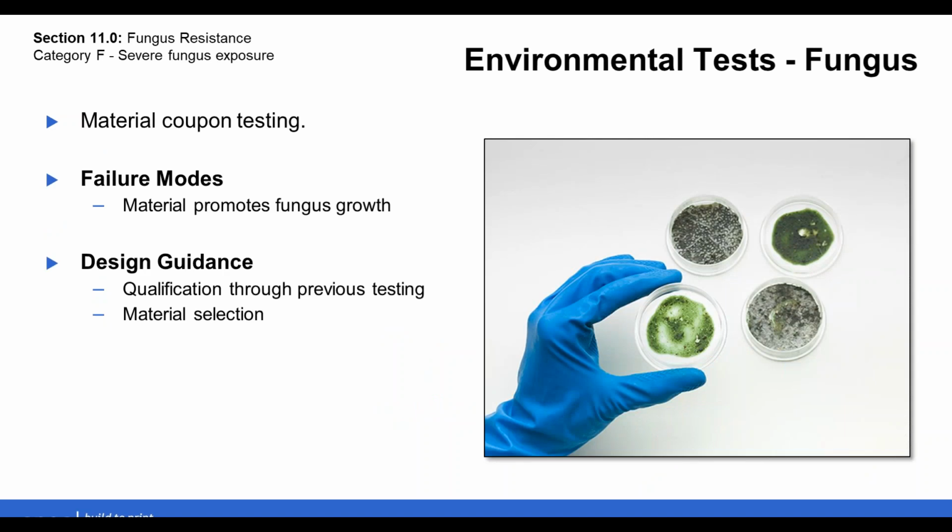Fungus test. It seems 9 out of 10 fungus tests can be waived or qualified through similarity or previous testing. There's tremendous amounts of data on the performance of certain compounds and their resilience to fungus. And if necessary, this test can be performed using a small coupon of whatever material is being used. Typically, the materials that are focused on are elastomers. If you have aerospace, aluminum, steel, etc., those are all exempt through the material properties themselves.